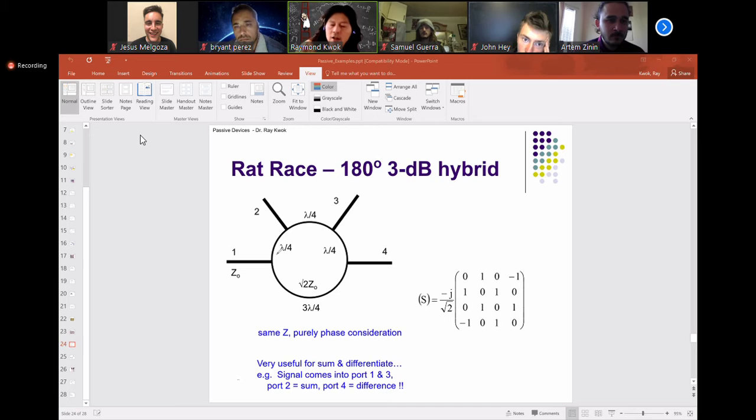It's actually because it's not a two port. I mean, it's hard for you to see, so look at this one, for example, right? You can think of this as 70 ohms, this is 50, so going into it becomes 100. This is 100, so this 200 becomes 50. I don't think you can look at a 4-port as simply 2 parallel lines, right? That's why I don't want to go into it. To solve for this, you actually have to solve the matrix to get the square root of 2 to get the impedance here. So right now, just say these are Z1. I'm just going to call it C1, right?